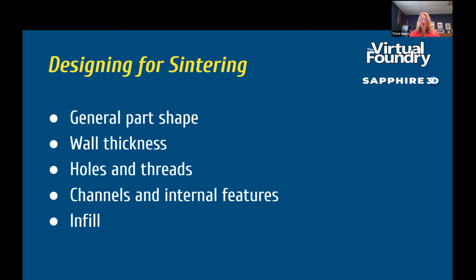So if you have pieces of your part that are sticking out, or it's a tube, you're going to want to make sure that you have that refractory ballast, that sintering powder, inside the tube or inside any openings that are not closed off, that you can have access to, and get that material in there to help support that shape during the sintering process.